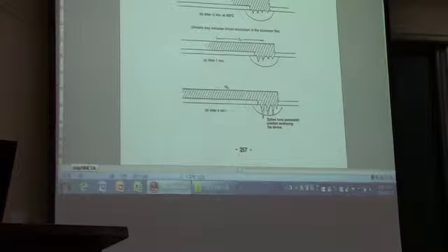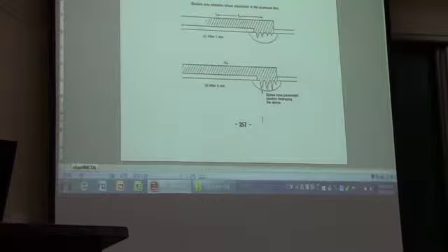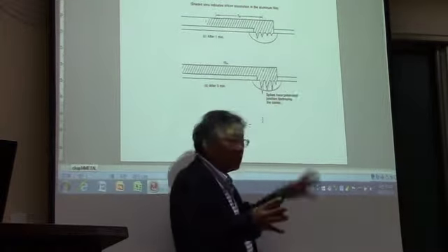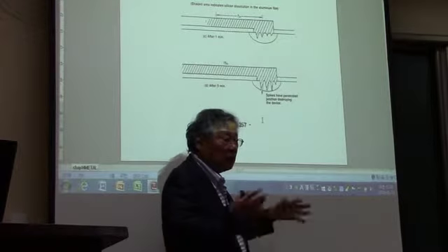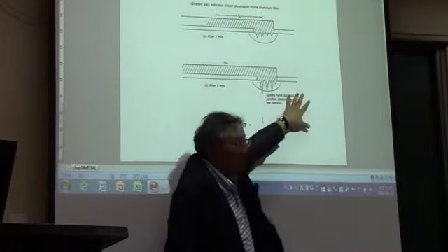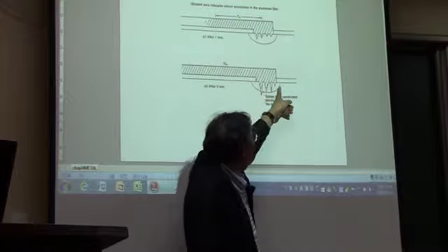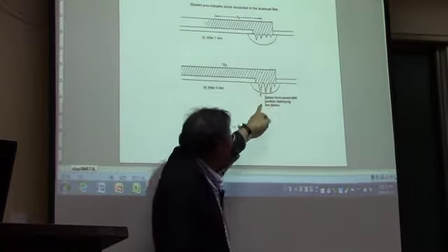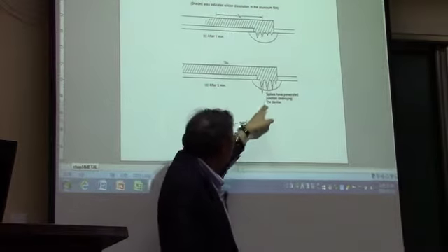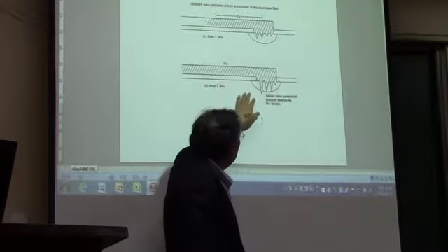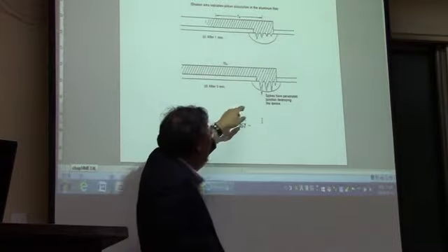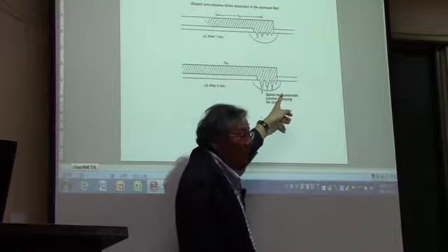And then within 5 minutes, you're going to see this is a junction depth, okay? You make junctions, you make source and drains on the silicon substrate. And then after 5 minutes, the aluminum goes deep into the silicon substrate, penetrating the junctions.